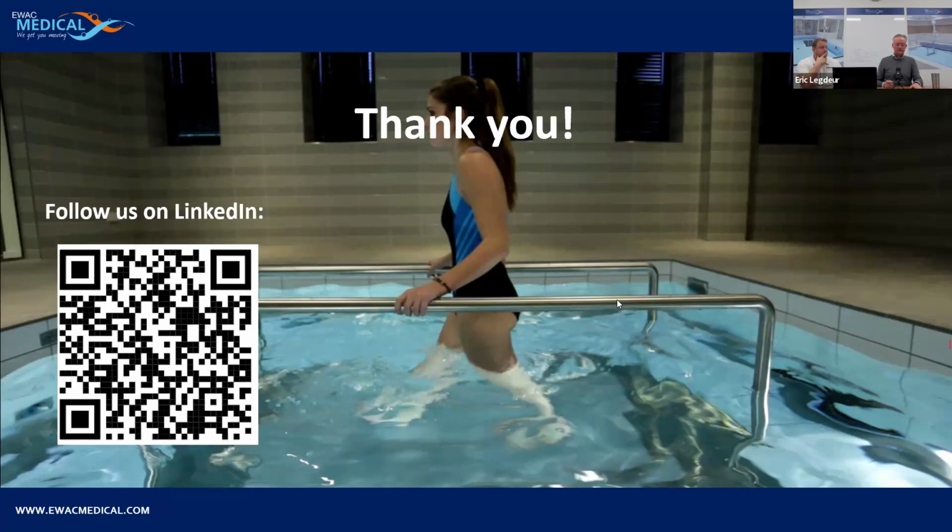That means that within 3 or 4 hours, the entire pool has been passed through the water treatment system. That's quite a lot of water actually. And you really need to maintain the chlorine levels that I have just referred to in the presentation. A free chlorine level between 0.5 and 1.5 is absolutely necessary to maintain a clean and healthy pool.